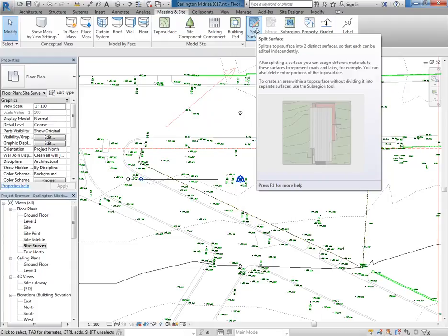Otherwise, I don't know if you've seen when you try to set say changes in your surface or your topography because of a retaining wall, and you often will have, you need to have points very close to each other, and you'll need often a series of very close points with one at say 2 meters and then another one next to it down at 0, so that it drops down suddenly, and that can be fairly fiddly.